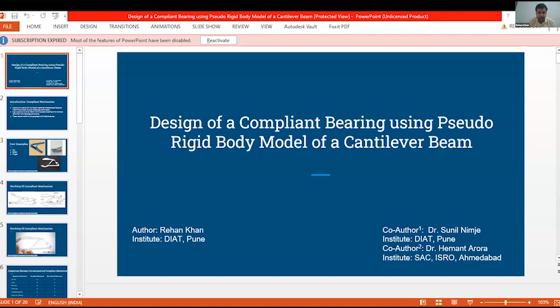At the corner of the cube, and this is the x displacement, which is a maximum of 4.81 mm at the corner of the cube. And this plot basically gives the von Mises stress. It is not visible here, since the maximum von Mises stress is developed at the base of the cantilever beam. The pointer shows that it is basically inside the slot.